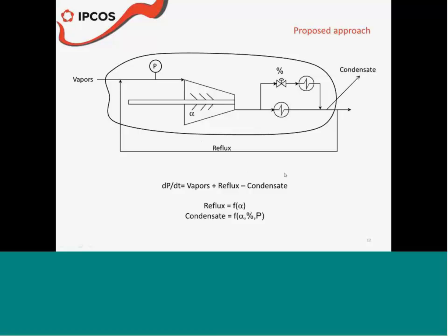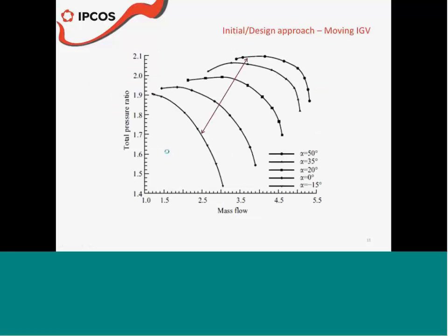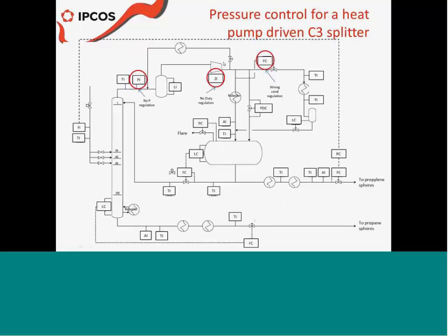So what we did was look at the whole picture, and not only the little part in which only the compressor and the vapors are considered, and we extended the envelope to also consider the condensate part. Let's go back a bit to the drawing. If you see here, the vapors are split into two. One part, the biggest part, is going through the reboiler, but there's a small part that you can actually regulate, how much you want to go this way, and it's going through a cooling water condenser, an auxiliary condenser.